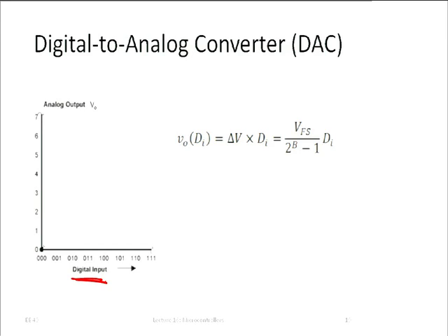Okay, so now the digital analog converter takes these numbers. In this case, it's only 7 different ones. It could be more if we had, for example, a 16-bit number that we wanted to convert. Here it's just 3 bits, to make my slide a little bit simple. It converts that to an analog voltage. Now, sort of reasonably, 0, 0, 0, we assign the value 0 volts. 0, 0, 1, we could assign, for example, 1 millivolt or 1 volt or whatever, right? And then 2 volts.